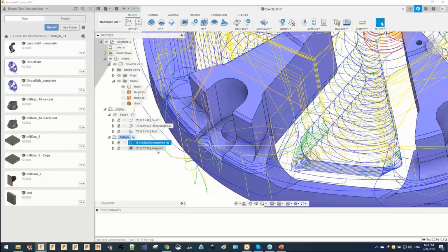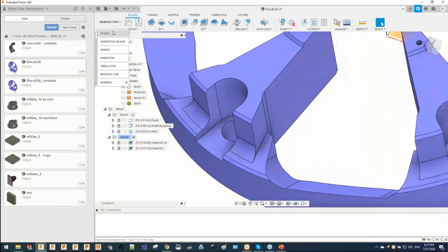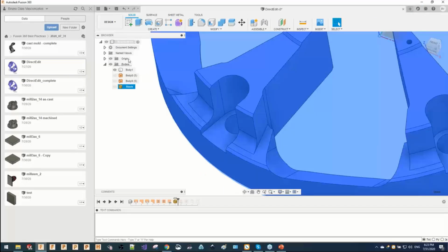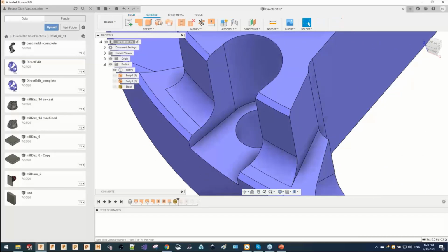When you're dealing with rest machining, even the simple surface or simple sketch you create sometimes makes the software ask you to regenerate the toolpath. And why would you need to regenerate if I have not applied any change to the model? In order to avoid those unnecessary regenerations, protect the toolpath. That way you can go freely to the design and create your surfaces. So that's what I'm going to do.